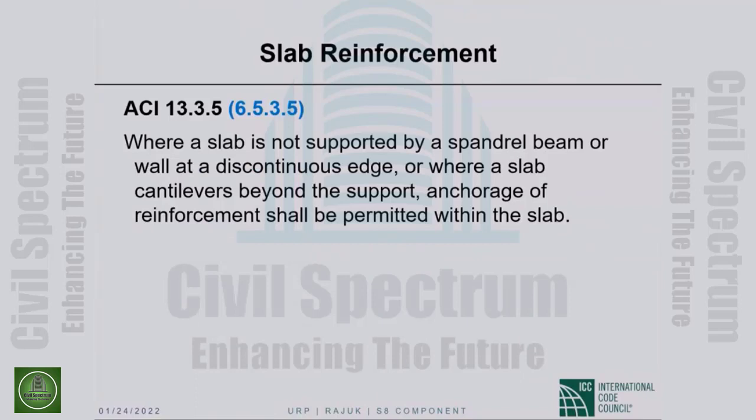Or where a slab cantilevers beyond the support. Now, anchorage of the reinforcement shall be permitted within the slab. Okay, so you will hook it inside the slab or go for headed bars or mechanical anchorage, whatever. So you have to anchor it within the slab.